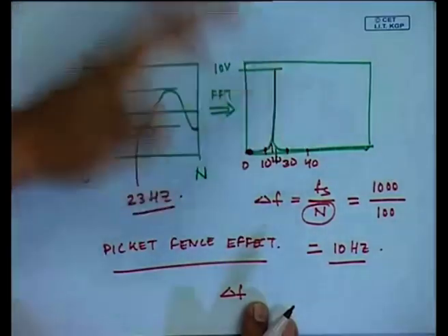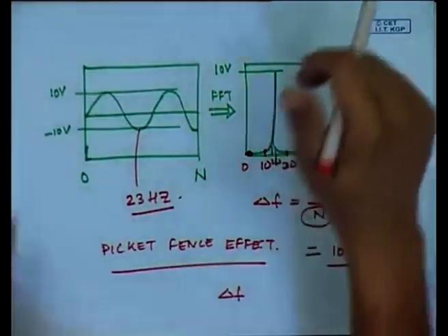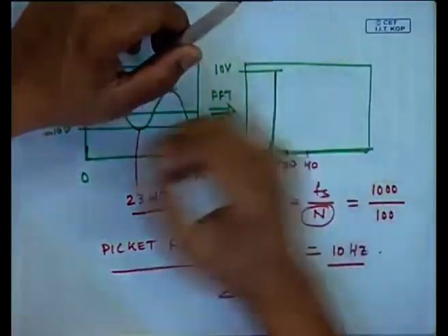If you do not see any frequency spikes coming up, you know you are not missing any signal, otherwise you are going to miss a signal. So, when you use an FFT analyzer, we have to be careful to play around with the signal, change the settings, see the number of blocks. How can I increase the block size?